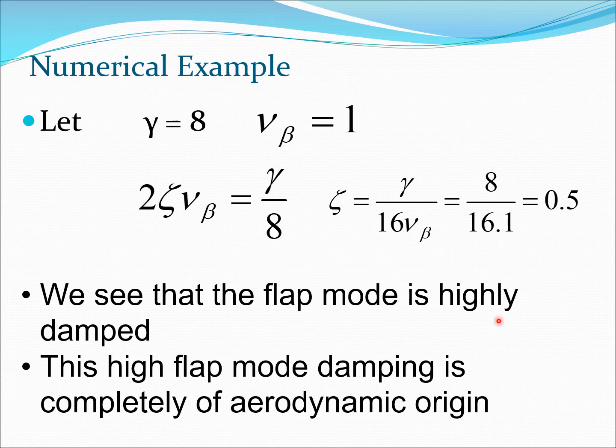This is an aspect of rotor dynamics which you need to remember all the time, that the flap mode is very well damped. The damping is essentially coming from the fluid mechanics, and therefore you don't need to bother much about the stability of the flap mode. We typically are doing all this to develop the mathematical tools to find out about stability. But in general, for the flap mode, we don't need to bother about stability. Of course, remember that all this would be slightly different or considerably different if you were on a different planet where the properties of air are different. So if you are on Mars, then things would change because the density of air there would be very low.